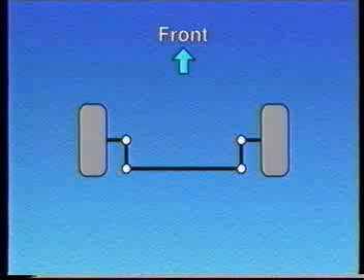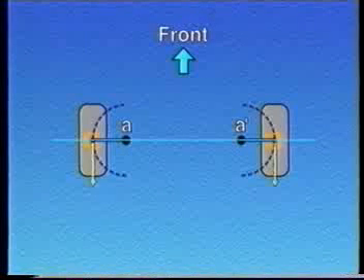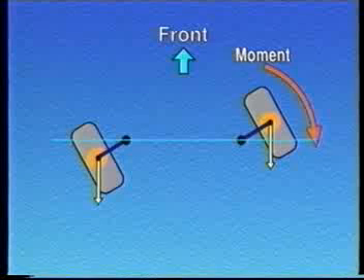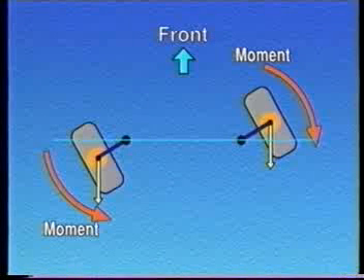Looking at the forces acting on the wheel-to-road contact area, it works like this. If A and A' are the steering axes when the wheel is turned, the arrows show the rolling resistance of the wheels. When turning the steering wheel from the straight-ahead position to the left, the moment functions on the right wheel to pull it back to its original straight-ahead position. The reverse but equal size of the moment which functioned on the left wheel balances this force, and the wheels remain where they are.